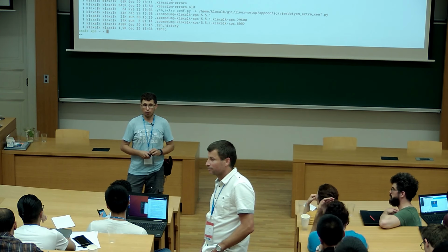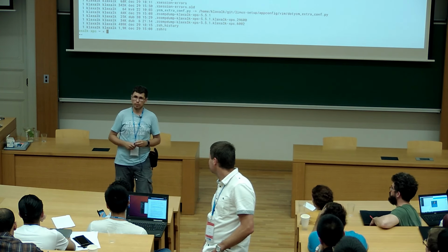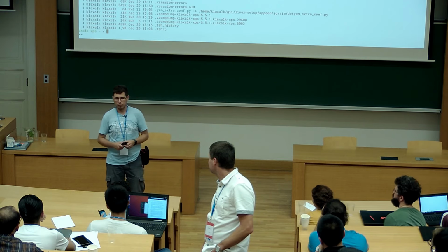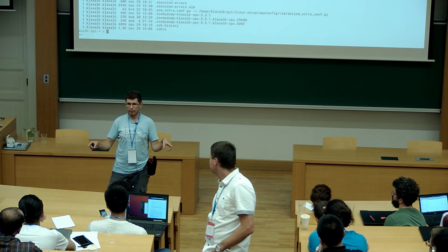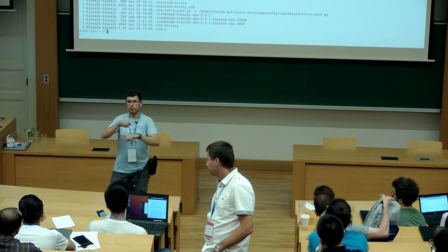Very good presentation. I would like to ask, where are you running the ROS master exactly? Is it on each drone? And how do you exchange the information? Yes, each drone runs its own ROS master, so they are independent. We use a slightly modified Nimbro network to exchange topics between the drones.